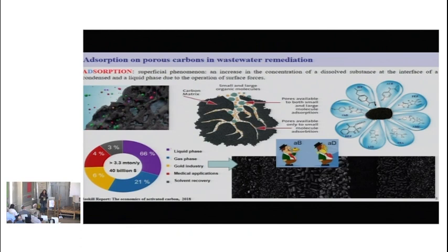And this is the beauty of the adsorption process, that they accumulate almost any molecule, so it's non-selective, meaning that when we have to regenerate, or if we want to, we can easily reverse the process, because there is no strong bonding between the molecule which is retained in the porosity and the adsorbent.